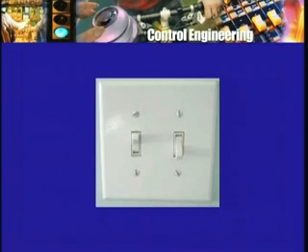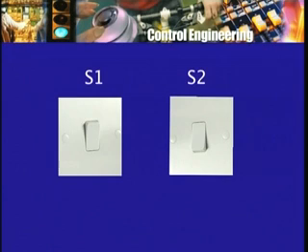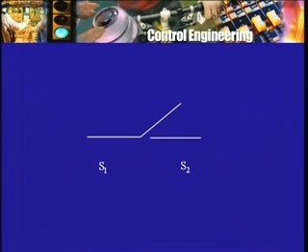There will be one switch and there will be another switch, and this one switch S1 will be opened at t equal to 0, and almost simultaneously with it this other switch S2 will be closed. S1 will be opened so that the battery or the cell is removed, and S2 is closed so that the RLC circuit remains closed, so that a current can flow in the circuit.